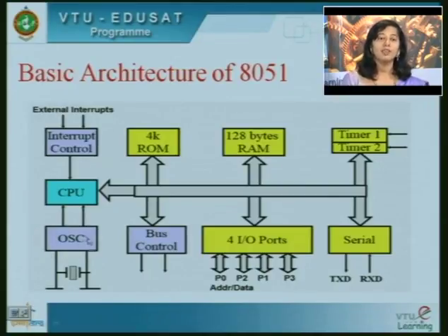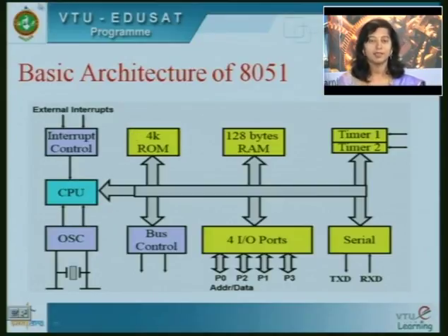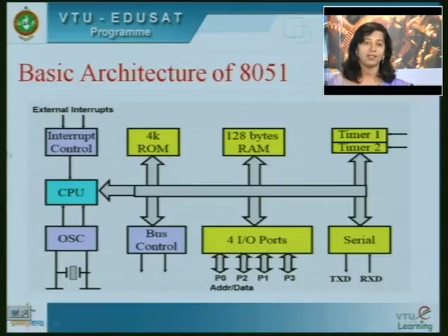Then everything needs to be timed to a given clock sequence. So, I need to put a crystal oscillator. You can see here OSC stands for oscillator. A crystal of different frequency is connected to synchronize everything to work at particular times. That is when I can use this oscillator synchronized to timers and everything. When should a read happen, when should a write happen, everything.